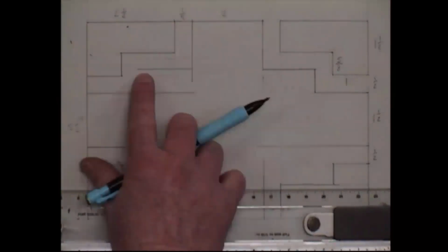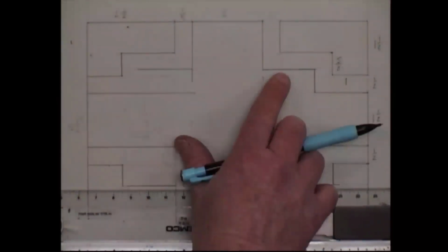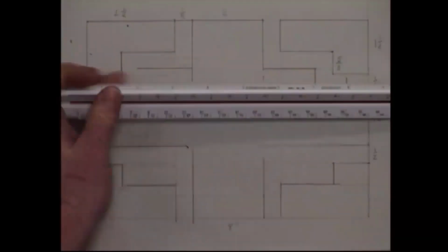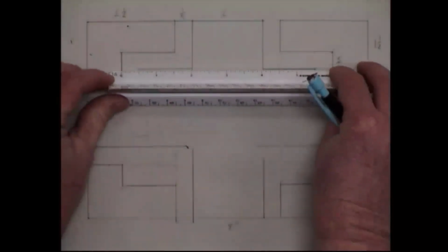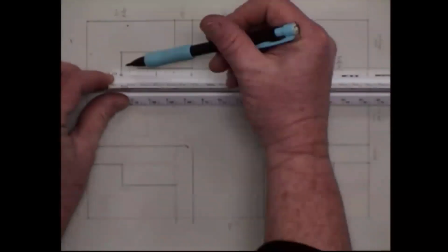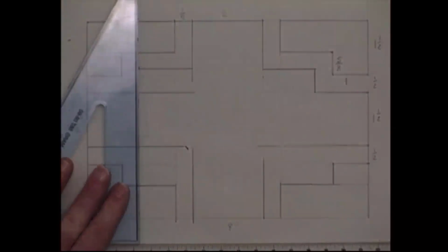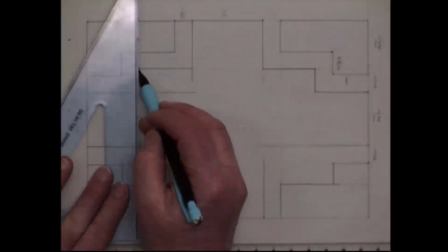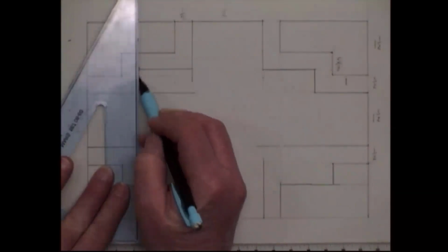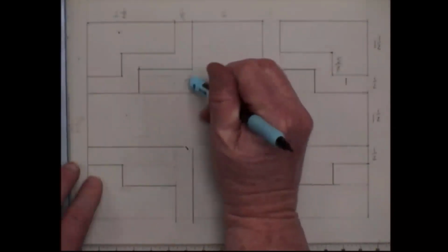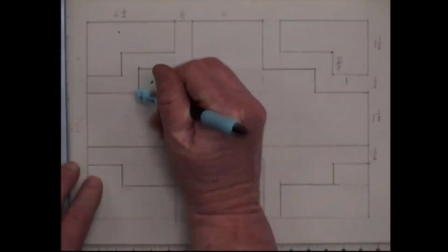So I have my line coming over from here. I do need to measure one time for my 1/2 inch away from the edge. So I'll just line it up with the line that I already have. I'll see that, okay, this is actually the 1/2 inch mark. So I was close. And then I'll put my straight edge in line with that mark. I'll bring that down. So again, I have my 1/2 inch space. I just erase what I don't need of those earlier construction lines.